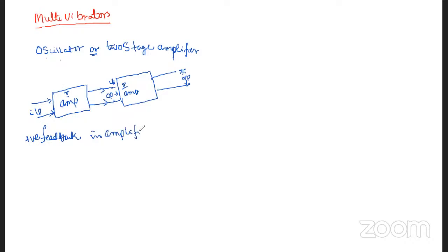We use positive feedback in amplifiers, which is supplied in such a manner that when one transistor is in the on position, say transistor T1, the other transistor T2 will be in the off position. This action is reversed after a time, depending upon the circuit conditions. That means T1 becomes off after a period of time, and then T2 becomes on. Vice versa takes place in this case.